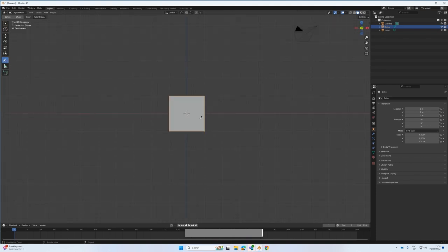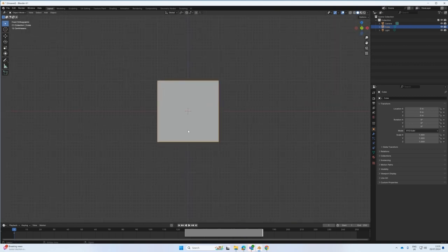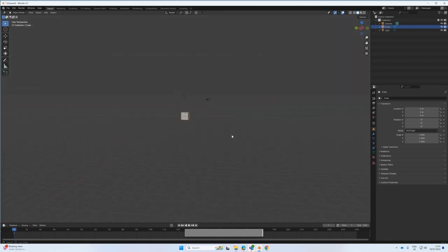So if I go back, the same thing, if I press 1, I'm looking down my Y-axis. If I press 3, that's my front view. It says here, front orthographic, so I'm just going to click that one. And if I press 3 again, it's right orthographic, which means it's my side view. And if I press 7, I'm going to see my top view. Sometimes we're going to use that quite a lot, so don't worry about it now. You just need to understand the 3D space.